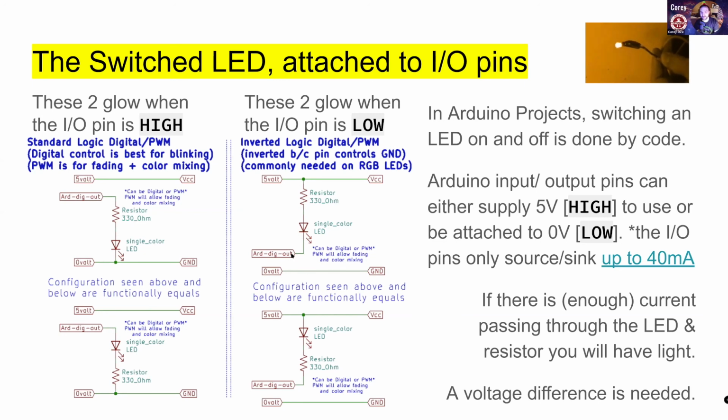If I write this high, which is normally what on would be, that means the top of the resistor LED pair is at 5 and the bottom is at 5. So 5 minus 5 is 0. There's not a voltage difference if I write this to be high. It's sort of like, instead of connecting this to the bottom, I connected it back to the top, which is weird.